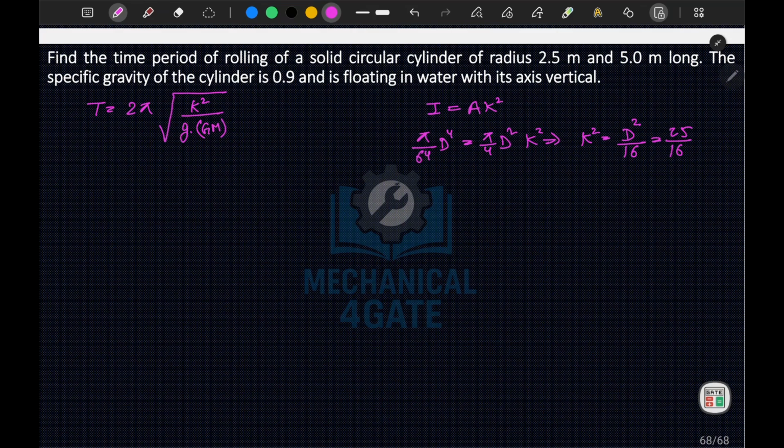Now what I have to calculate is your GM. We know that GM is equal to BM minus BG. BM is I minimum by volume of fluid displaced, that is pi by 64 into d to the power 4, that is 5 to the power 4. The diameter is 5 meter and length is 5 meter.